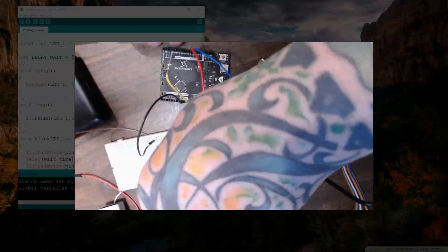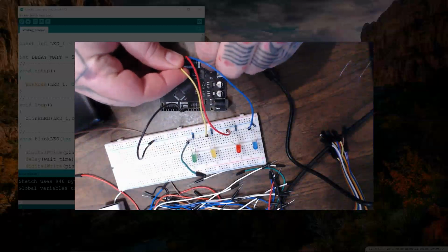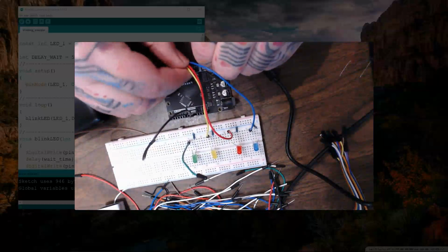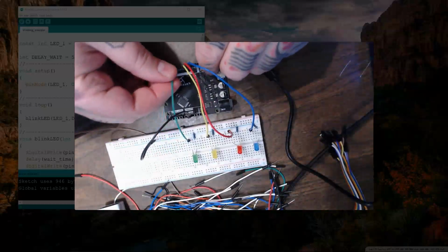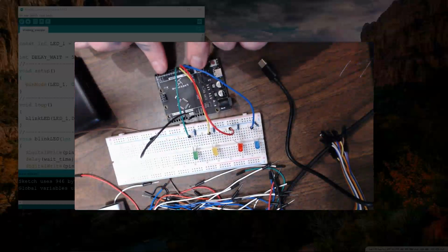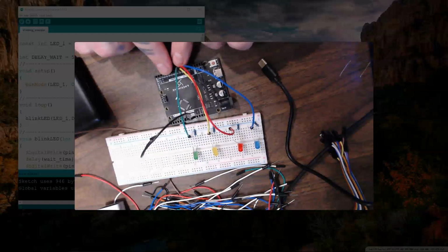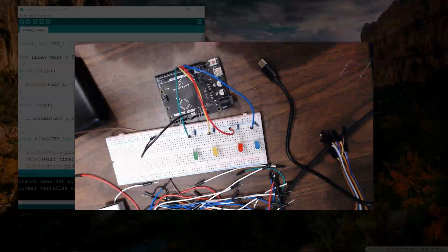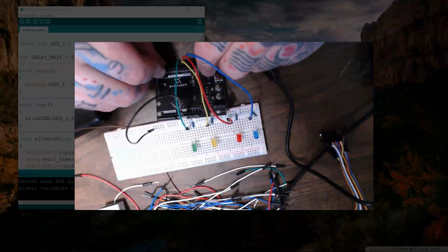So we will get the green, and you can see the fun of doing this as everything starts disconnecting while I hit stuff. Oop. And green right next to that one after it. So if we follow that, blue is in pin 12, red should be in pin 11, the yellow should be in pin 10, and then green should be in pin 9. I'll just take a look and confirm myself.